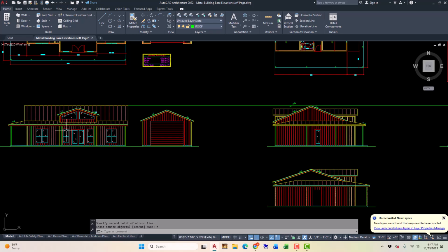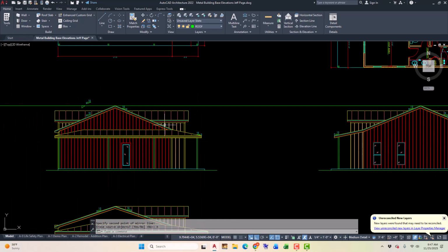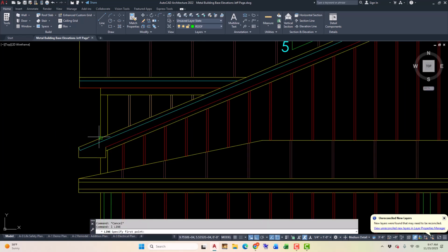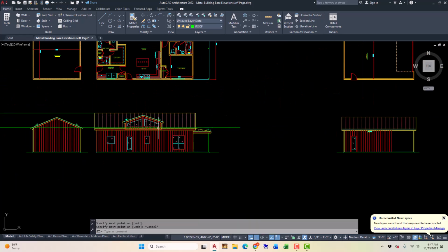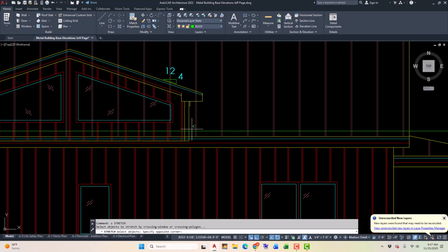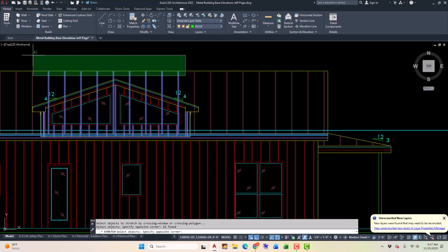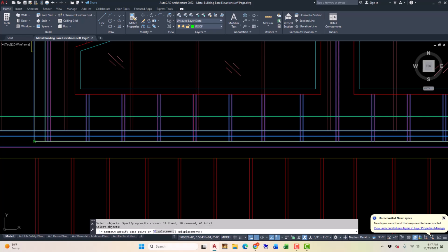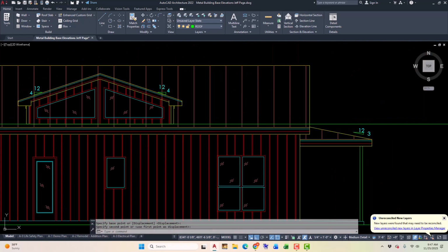That's because this one has the porch sloping up like we showed here, and it kind of gets in the way. So what we have to do is come in here where this face of the back of the house meets this roof edge. I'm just going to draw a line all the way across, and that lets me know that I need to stretch this guy up to that line, the green line. So this is actually where that would sit.